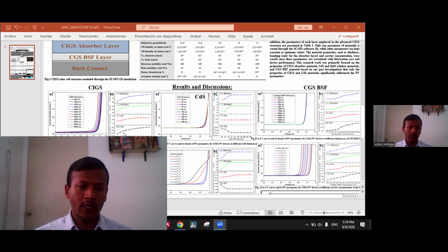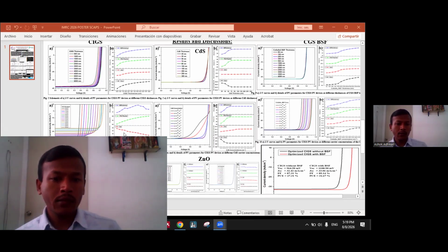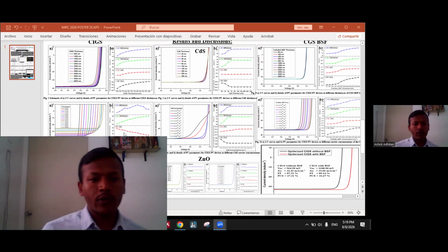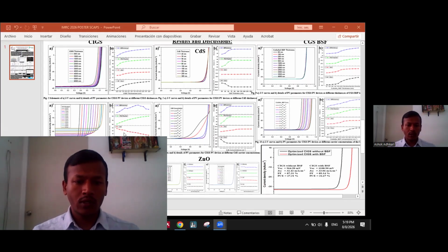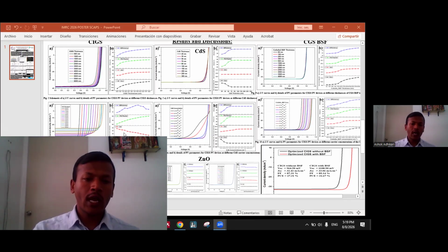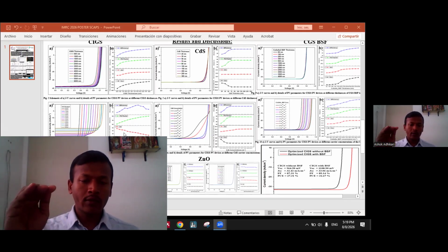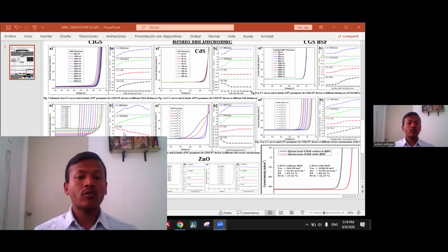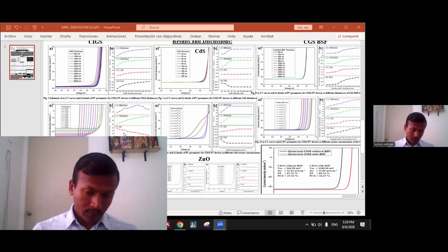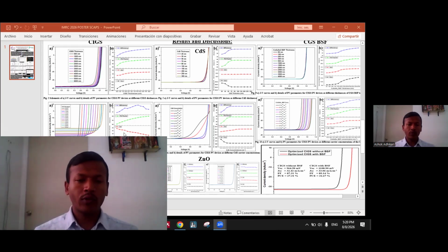consequently the efficiency. Figure 3 is related to varying the band gaps. There are some changes within a certain range; up to 1.4 eV it increases to higher efficiency values, and after that it decreases. The decrease is related to the decrease in the short circuit current density, since with a higher band gap, the absorption of the incident photons will be lower.